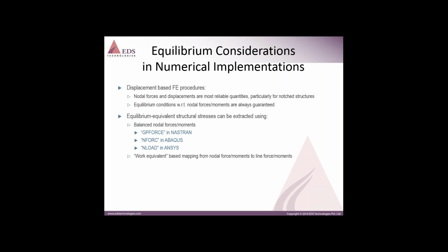A little more precursory information here. There are some things we need to consider when dealing with numerical implementations. One is that the most reliable quantities you can get from a finite element procedure are the nodal forces and the displacements, because the equilibrium conditions are always going to be guaranteed.